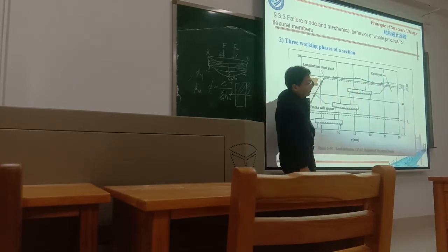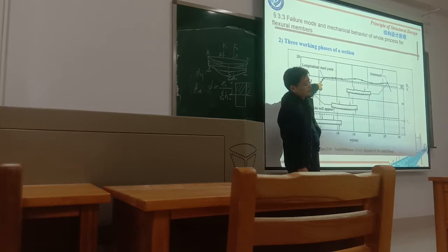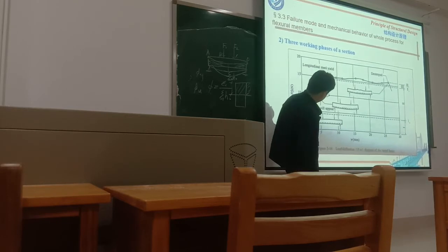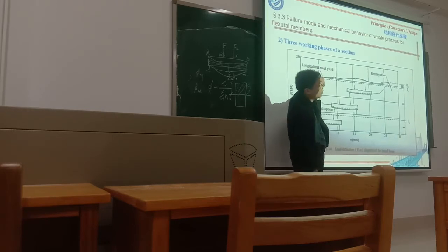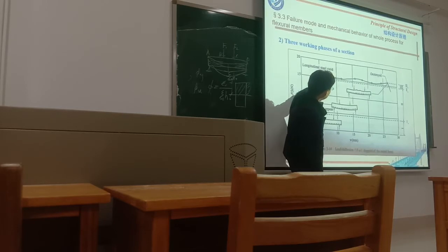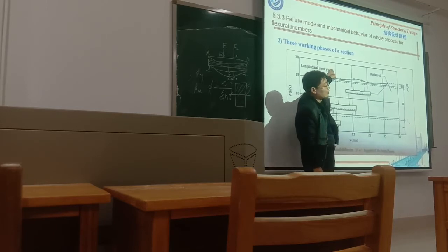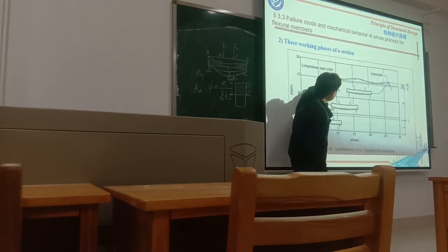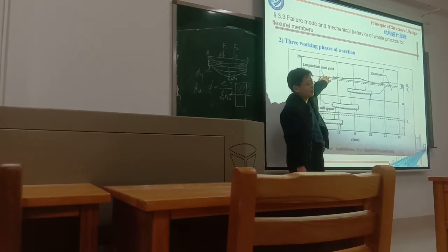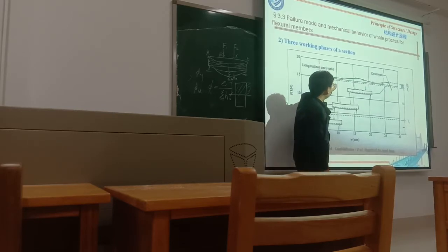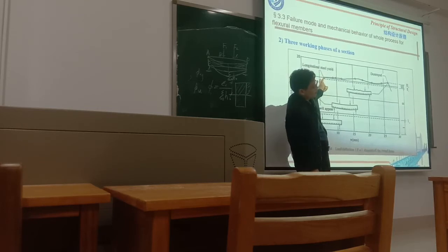For the over-reinforcement beam, the steel has not reached its yield strength. It will still go up, but when it's going up, the concrete has already crushed.